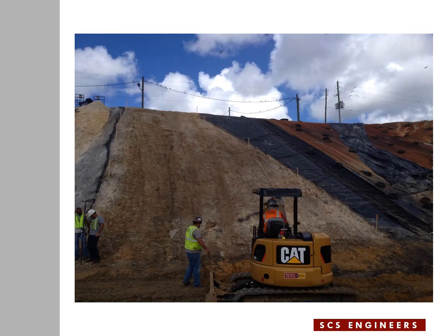Here it shows the geosynthetics to the right side of the repair area where the stakes are. They have cut back the geomembrane and the geogrid to expose the soil below it. To the left side of the repair area you see the cut line in the geosynthetics and the stake marks. So the area in between the two stake marks extending from the top to the bottom of the slope is the repair area. New geosynthetics are going to go in and tie to the existing geosynthetics on the two sides of the repair area.